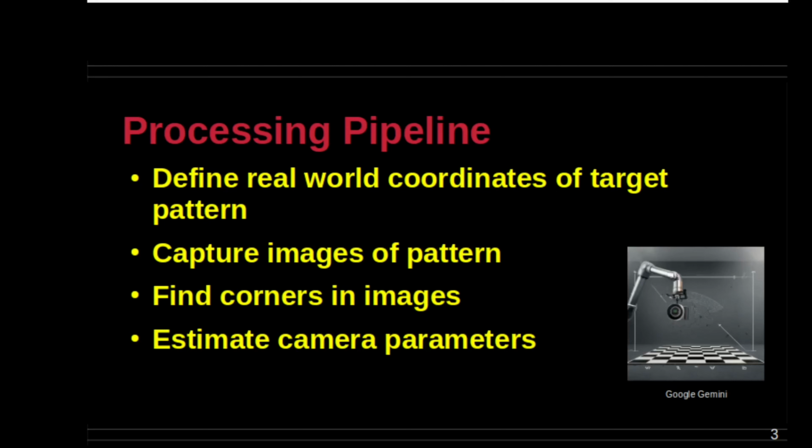The checkerboard is viewed through the camera at different positions and angles that are captured and saved as files for use during calibration. Since the detection of corners in an image is a prerequisite for that image to be used during the calibration calculations, it is best not to save an image whose corners cannot be detected.